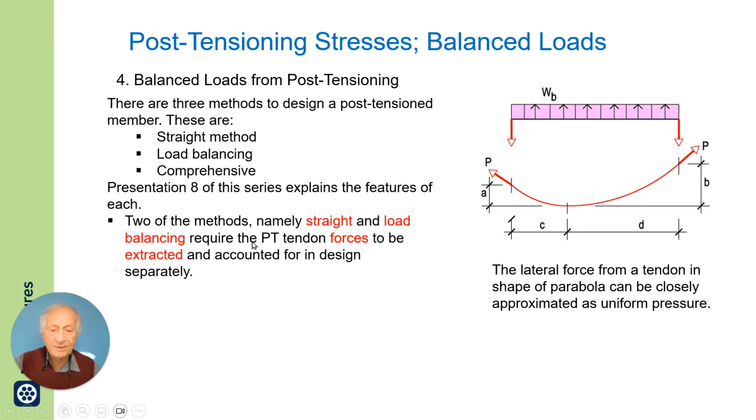Two of these methods, namely the straight method and load balancing, require that the post-tensioning forces be extracted from the member and accounted for separately. You have dead load, you have live load. Also, in two of these schemes, you will also have post-tensioning force. And the post-tensioning force is referred to generally as balance loads. The next couple of slides are going to talk about this.